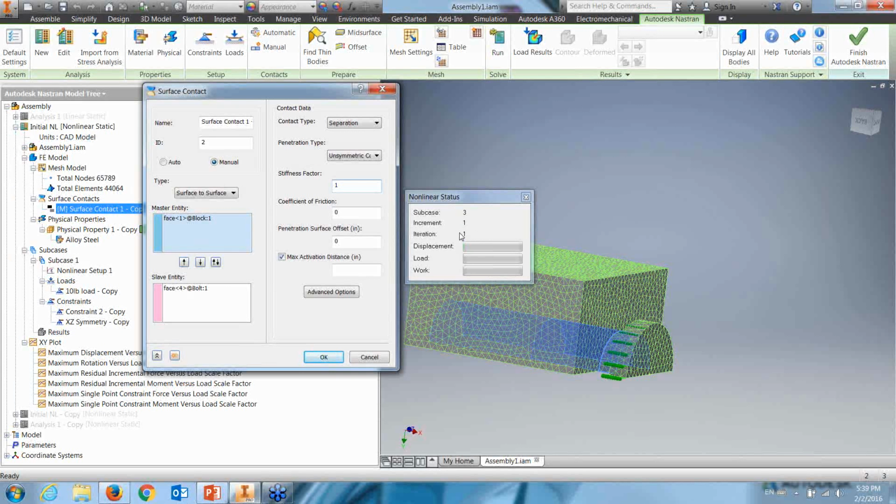You could go past the number of increments if you start sub-incrementing because you're not converging. Say you've specified 10 increments, but it needs to cut your load down because it's reached the maximum number of iterations for that increment, and then it decides to cut things in half. So you may end up with more increments than you initially intended.